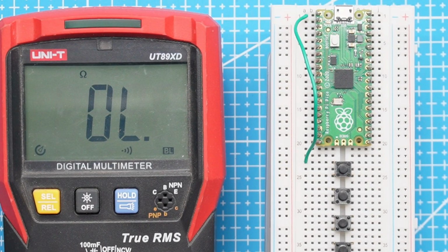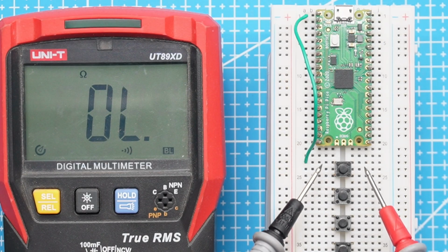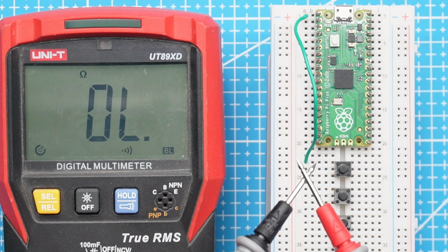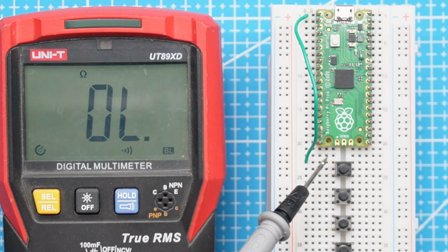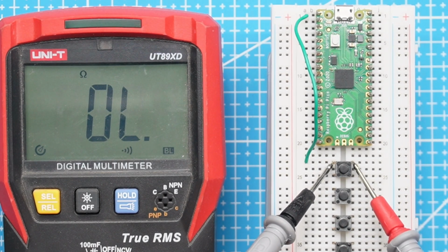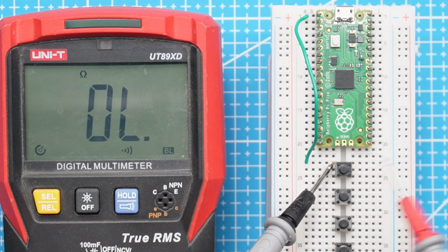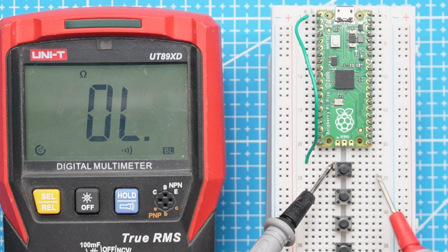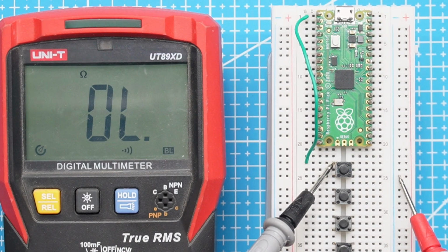Here we have a multimeter, and we're going to test the connectivity of these buttons. So you'll see if I touch these 2 probes, it makes a beep sound. So if I connect this to the top one and the top one here, you'll see there is a short between them. But here at the bottom, there will be nothing. So when we press this button, then the electricity will flow through here, through the button, through this leg here. And we're going to connect all of these bottom legs to ground.